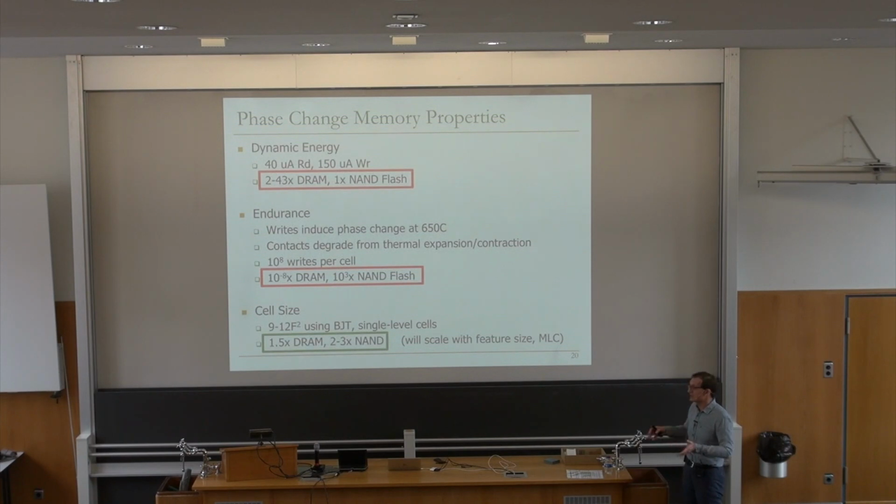Very high density, but reliability and endurance are very low, because you chop up the voltage range in flash memory into essentially 8 different levels. And as a result, you have an endurance problem. Okay, but this is better than flash, which is good, but it's not as good as DRAM. So DRAM technically is supposed to have an endurance of infinity.